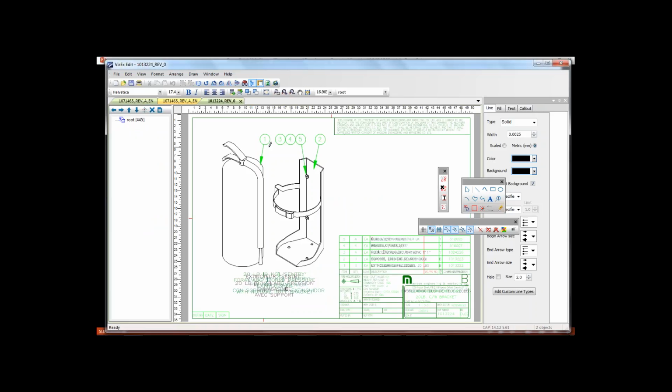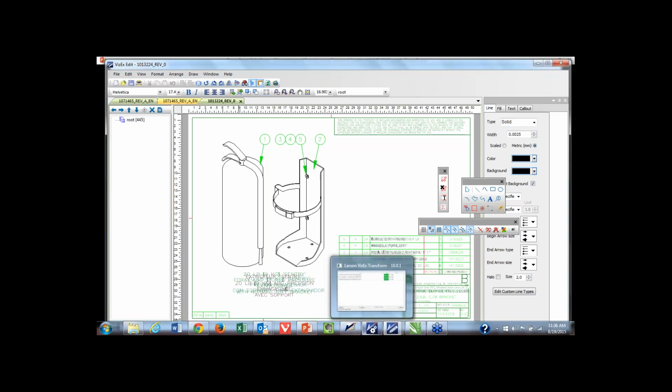You really need to think about how you're going to do that. Can I do it in an automated way? I could do it manually. I could have eliminated the layers using VisX Edit, but that might not be possible in every software that you're using. So just bear in mind, if you're using DWG or 2D CAD, that you might need to get rid of extraneous information.